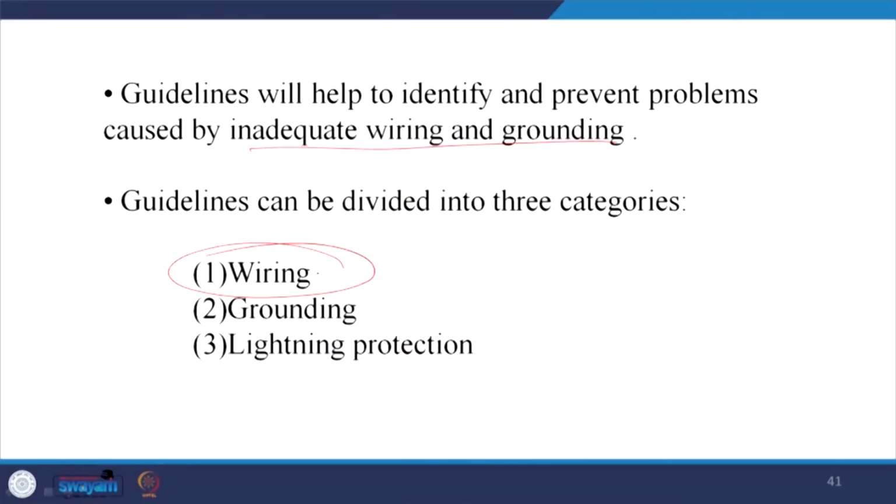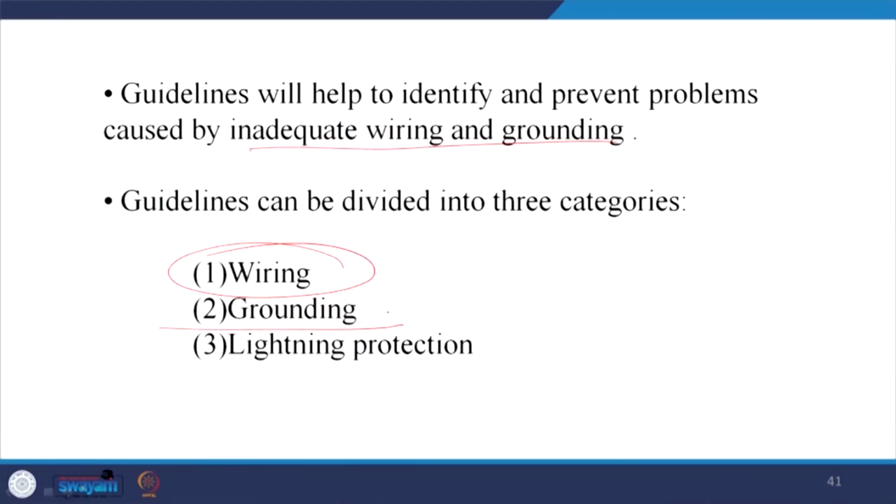Moreover, if some portion has adjustable speed drives, then try to contain the adjustable speed drive harmonics and give them a sink path, so that they do not propagate to the whole power network. Thereafter, grounding has to be done very properly. If high current is required to sink through the ground, the neutral may burn.